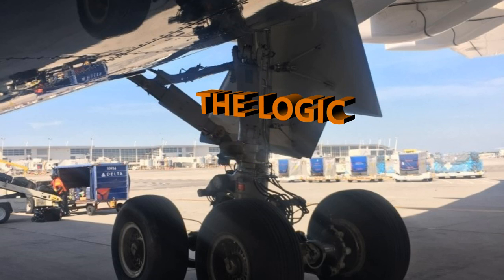All right, let's go a little into the logic. The logic is you have your nose landing gear and main landing gear compressed. You have at least one engine master lever in the on position. Remember, we talked about the yellow hydraulic system. This is what we're dealing with here. The main landing gear, if you recall, is drawing its supply from the green hydraulic system. And then another aspect to the logic and conditions is your towing lever is not in the towing position.